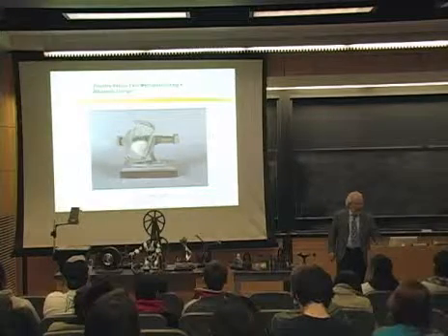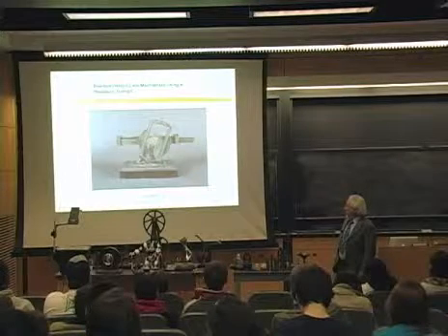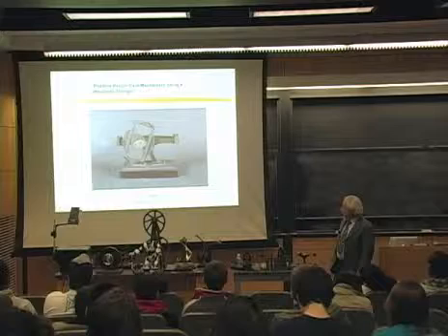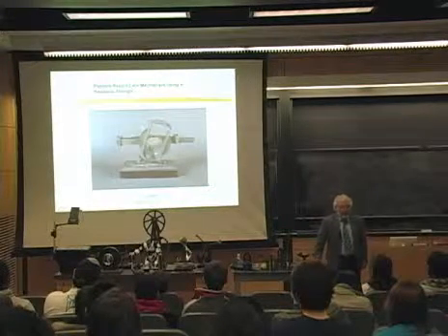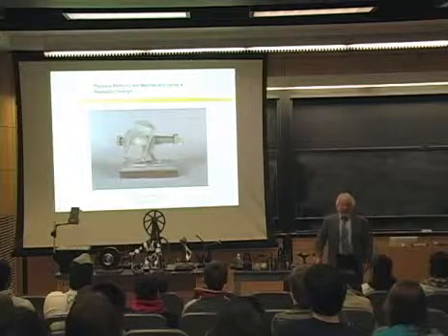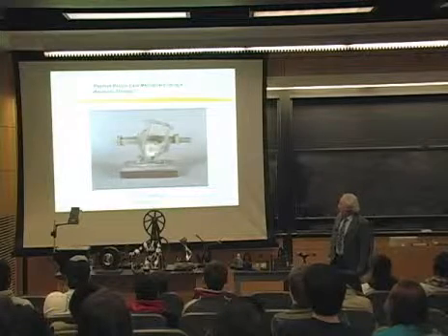And this is a cam mechanism. And in this particular cam mechanism, there's a dwell at each end of the cycle. So, in fact, the shape of that cam is called a Reuleaux triangle, and we'll talk about that in the next lecture on how we can create a device that has a pause.